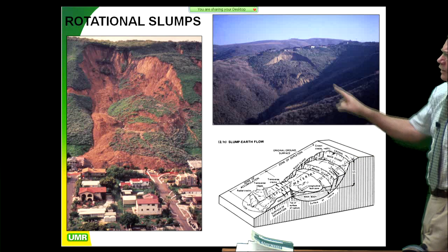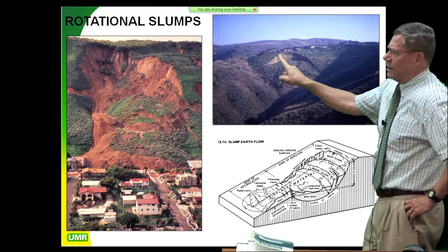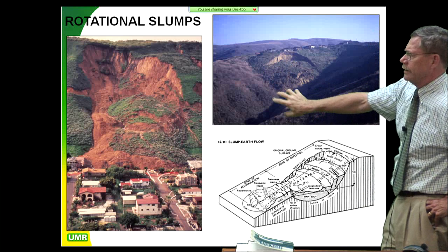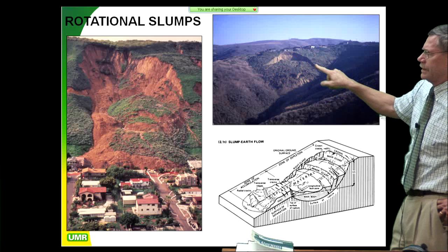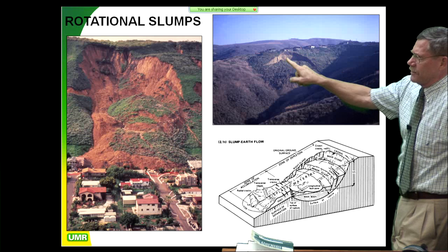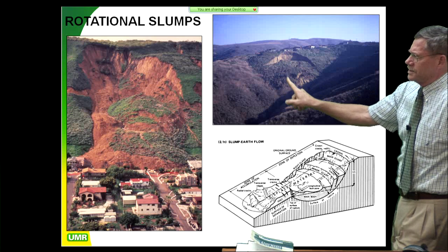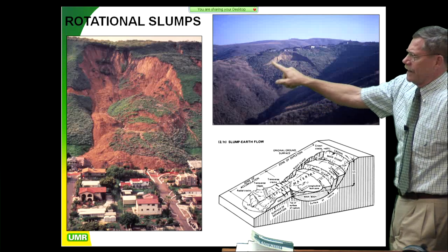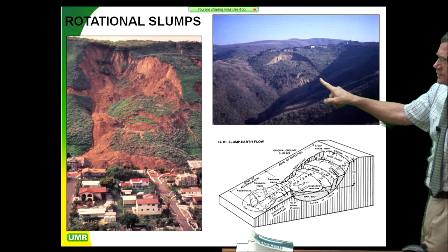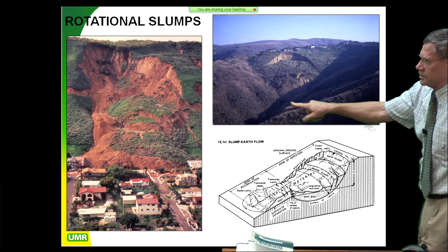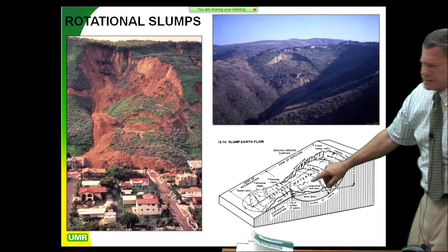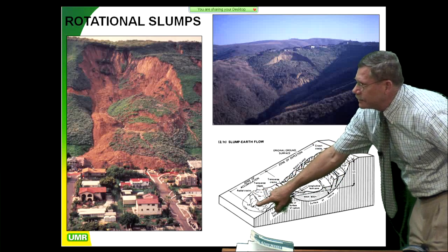One of the things you want to look for is an arcuate scarp. An arcuate scarp occurs through tension. You have a universal pulling away, you get an arcuate type scarp. Notice that the height of that scarp, the exposed scarp, is greatest somewhere near the middle, near the center of the slide mass typically, and then it diminishes in either direction coming down. Then you have lateral scarps, which are a little harder to follow, and then you actually have toe scarps of sorts here. They actually just call it the active landslide toe down here.